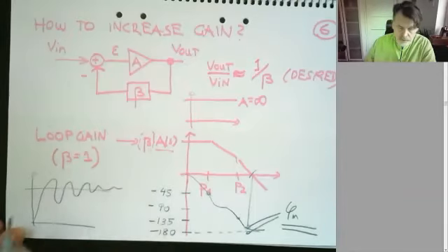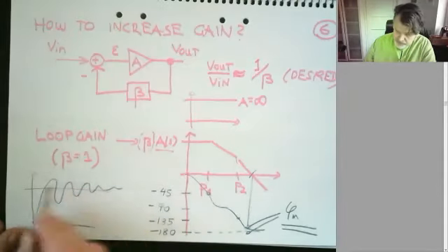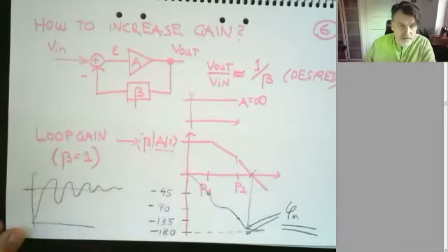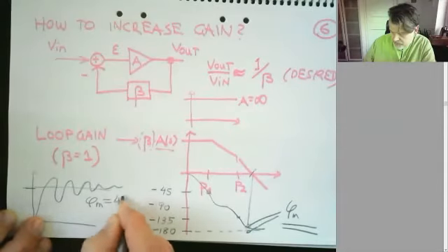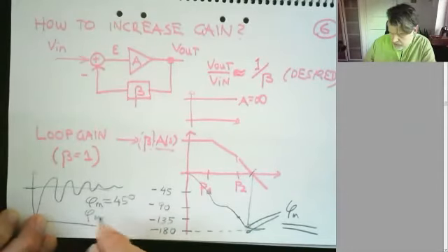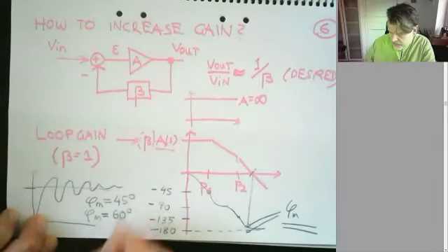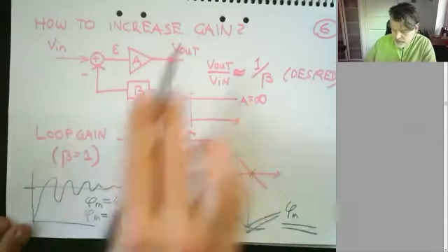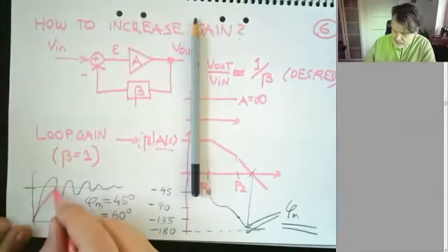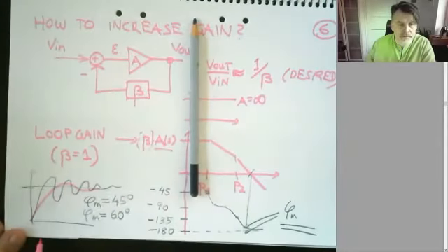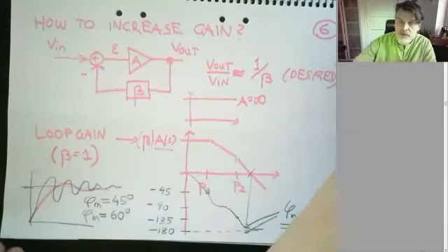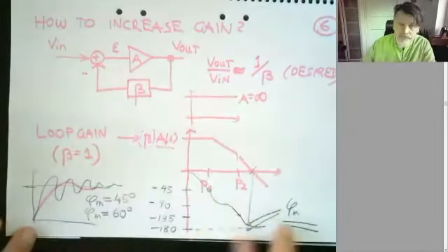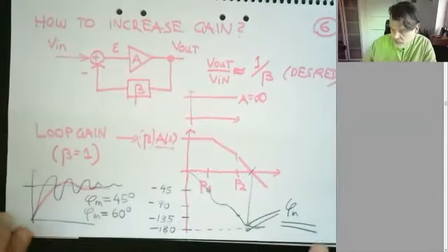So the number of fluctuations around the final value will be a function of the phase margin. And we typically design them to be 45 degrees, or more conservatively 60 degrees, which will give you quite nice settling behavior like this. Once again, we will come back to this when we discuss switched capacitor blocks. I just wanted to give a very quick background here before the break.